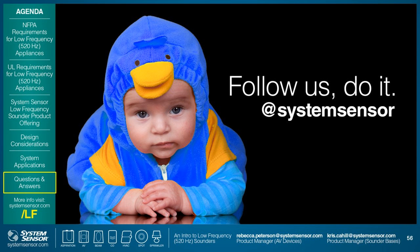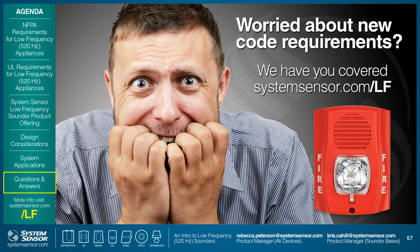A couple of questions on current draw. How do the low-frequency AV devices compare to standard devices of a similar type? Rebecca? Our low-frequency sounder only, if you compare it to our SpectrAlert Advanced horn-only HR, the current draw is almost double.